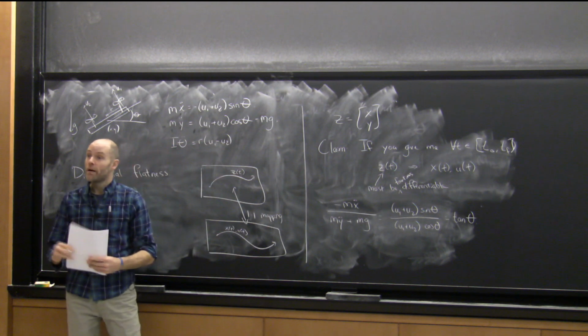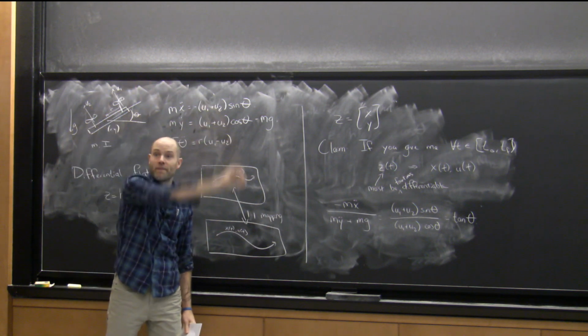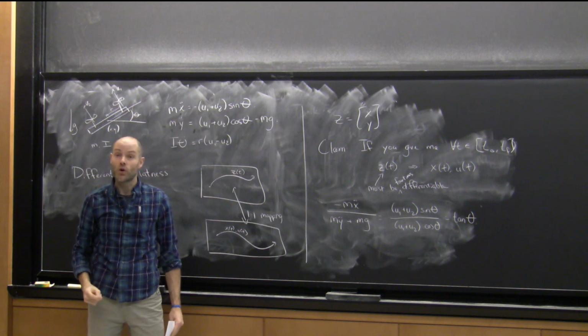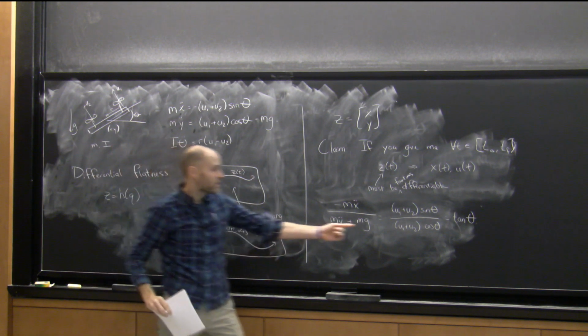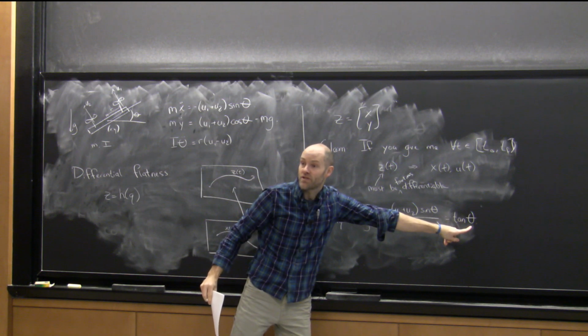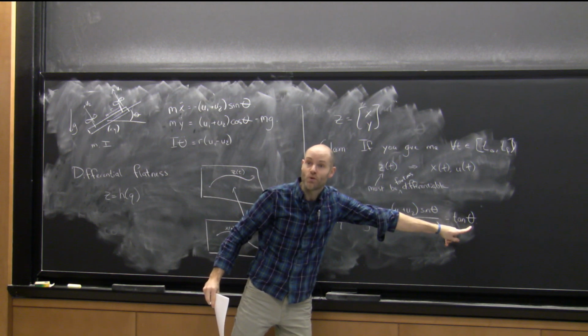So just by virtue of you telling me what the center of mass had to be doing, if I look at the accelerations that the center of mass is going under, it tells me what angle the quadrotor must have been at to accomplish that, because there's not enough motors to do more.